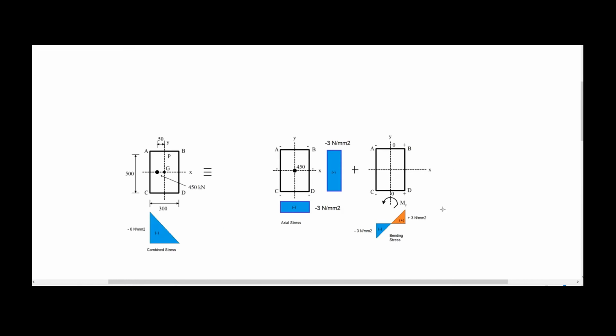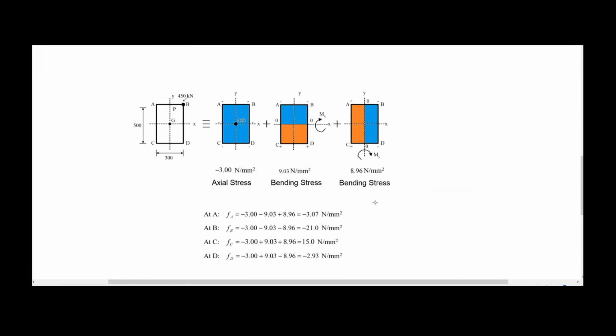The diagrams I did in here for these cases can be done as well in both directions for this problem we have in here. So we are going to have a rectangular distribution of the axial stresses in here and in here. We are going to have linear distribution of the stresses in this direction for Mx and in this direction for My. And we can combine these diagrams to have a set of two diagrams in two directions for the combined stress in this original cross section, which is the interest for us because this is the analysis we are doing.